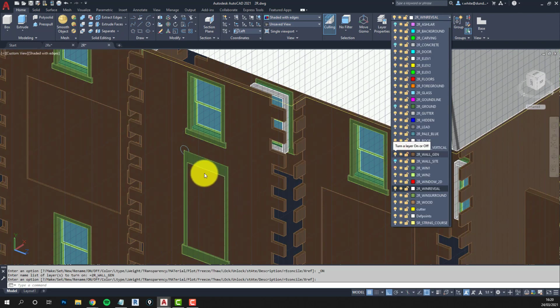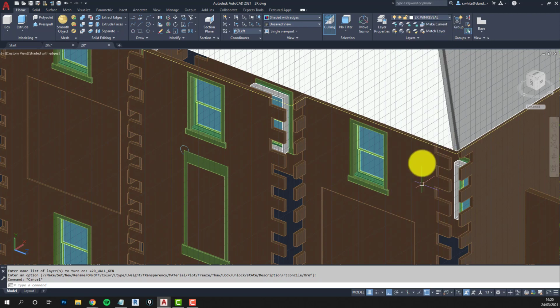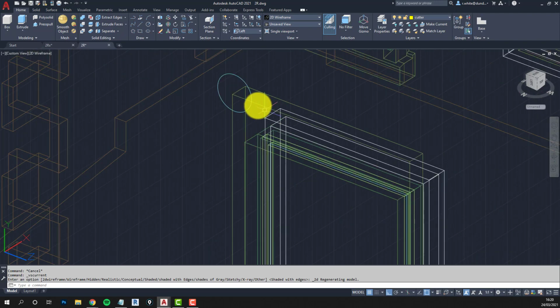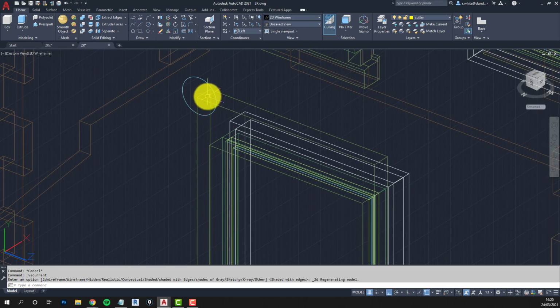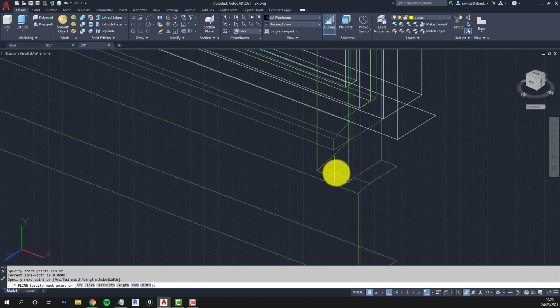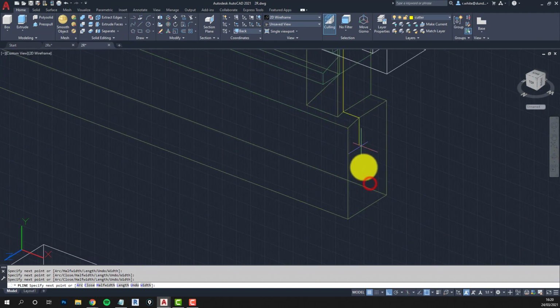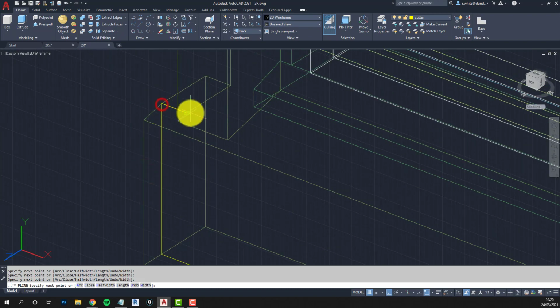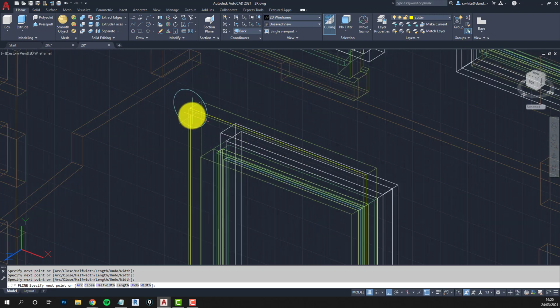Okay, wall general, you can see we haven't got a hole for the window. It needs to be punctured through the wall. So I've got a layer here that I use for that nice bright colour. I call it a cutter. So we just need a polyline around the overall window shape. We need to be on the back UCS, polyline from the center here. So I'm tracing around the window surround. Notice the polyline doesn't deviate, doesn't go in or out. Okay, and close.